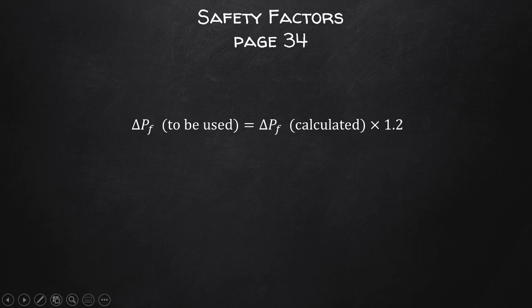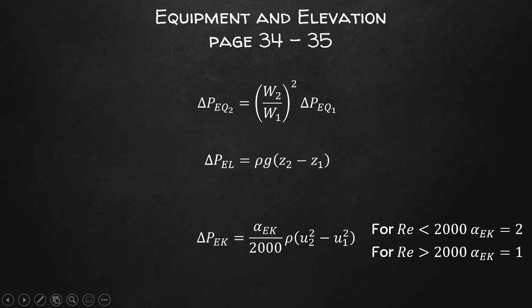Right, so equipment usually has a specific pressure drop that applies at a specific flow rate. So let's say this filter operates at a flow rate of 1 kilogram per second. As with other pressure drops that we have discussed already, pressure drops at other flow rates can be prorated for by squaring the ratio of the new flow rate that is of interest and the reference flow rate.